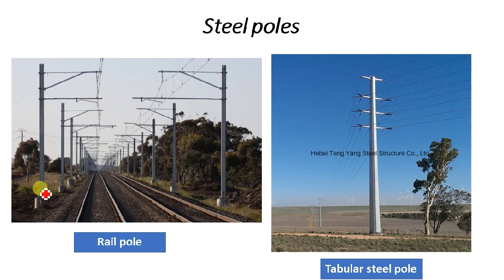Now the length of this kind of pole is somewhere around 7 to 10 meters, and most of the part, about 1/6 of the pole, is buried in the ground. Here you can see that the muffing is provided, so the pole is very strong. This kind of pole is generally used in the case of around 33 kV.